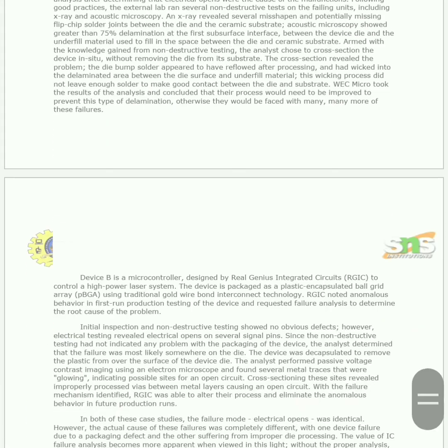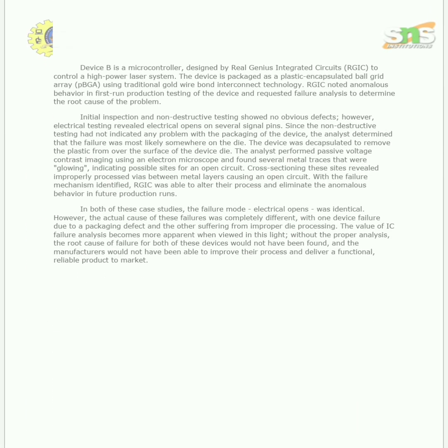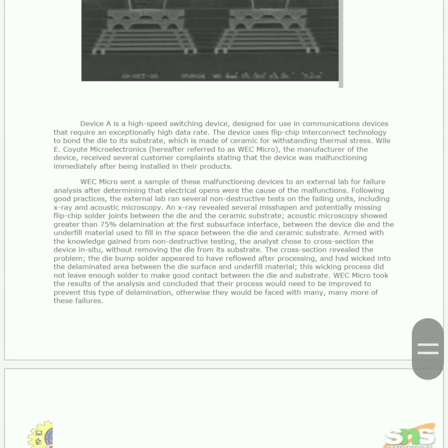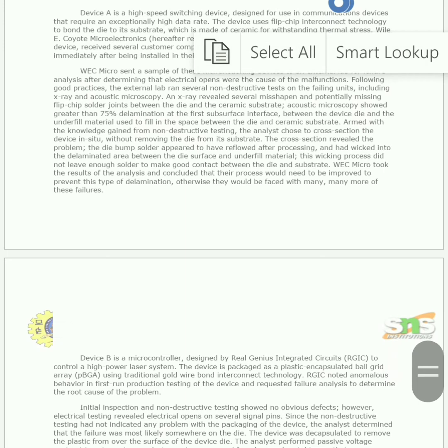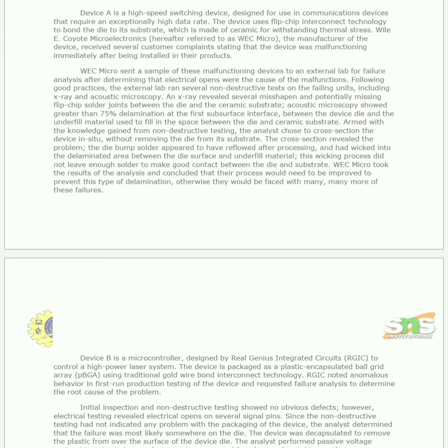RGA noted anomalous behavior in first run production testing of the device and requested failure analysis to determine the root cause of the problem. Initial inspection and non-destructive testing showed no obvious defects. However, electrical testing revealed electrical opens on several signal pins. Since the non-destructive testing had not indicated any problem with the packaging of the device, the analyst determined that the failure was most likely somewhere on the die.